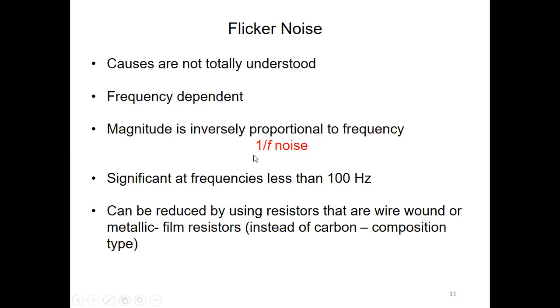So it is significant at frequencies less than 100 Hertz. Why? The magnitude of the noise is inversely proportional to frequency, 1 over f. When the frequency is lower, the magnitude of the noise is higher.